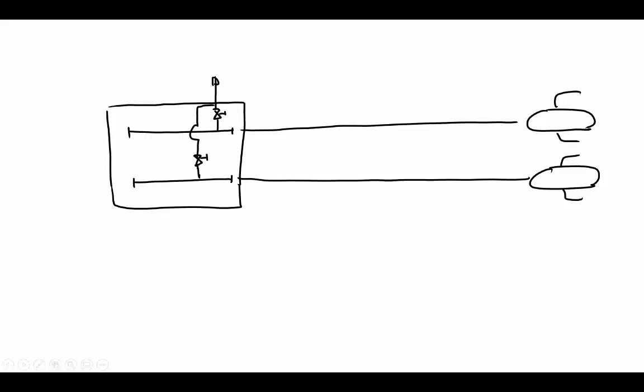Okay, so you see that if you have this configuration, you can very easily pick this line and send the pig from one end, and then return it through the other end. But then what you need is to have this pigging valve or crossover valve, and it has to be fully open. And the valves to the wells have to be closed, such that in this case you can pig from this side, do inspection, wax scraping, anything you need to do, and then you return through this line.